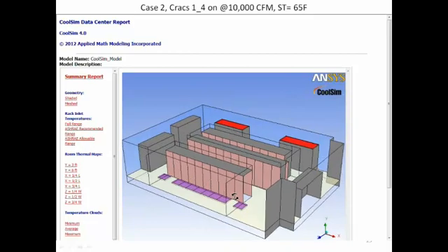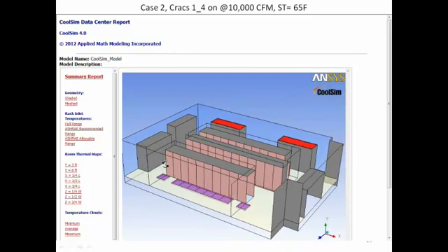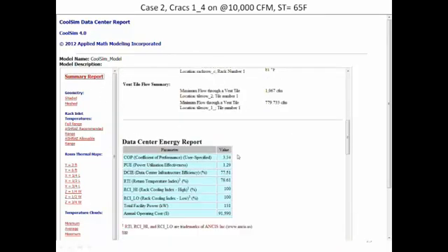When we go up 10 degrees in temperature, we improve the efficiency by just about 20%. It's a good rule of thumb. It's about 19%. Good rule of thumb to remember. If you can move your supply temp up 10 degrees, you're going to get about 19% energy improvement out of the heat rejection system. And it shows up right in the coefficient of performance.